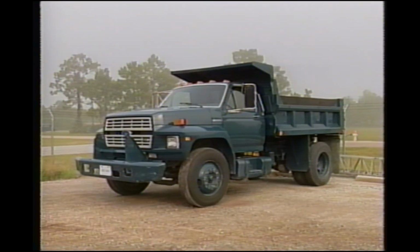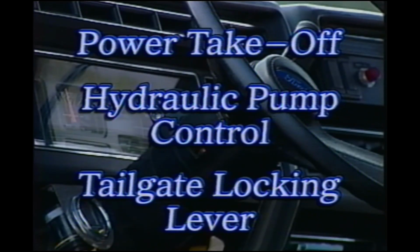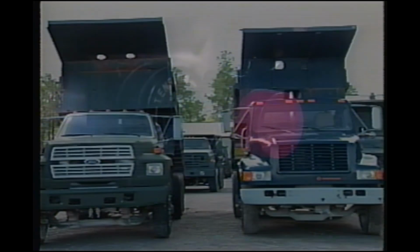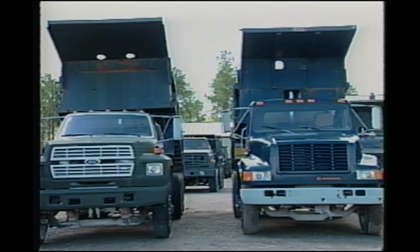Let's take a look at the different controls used to dump or spread material. The three controls are the power takeoff, hydraulic pump control, and the tailgate locking lever. Both the PTO and hydraulic pump control are found in the operator's cab, either mounted on the dash or located on the floor. They may be switches, levers, or knobs, depending on the manufacturer.